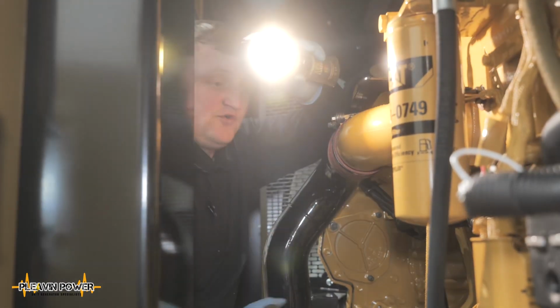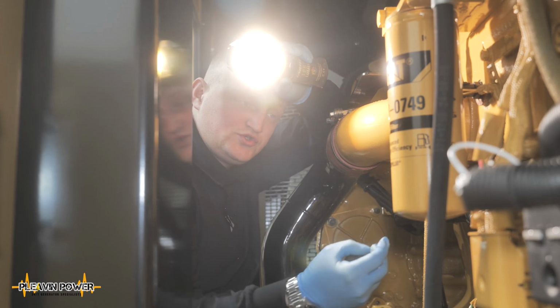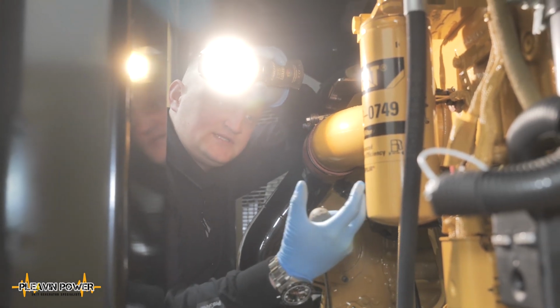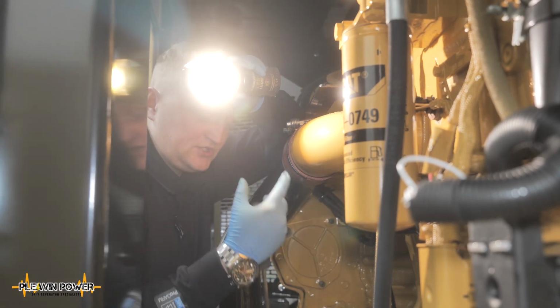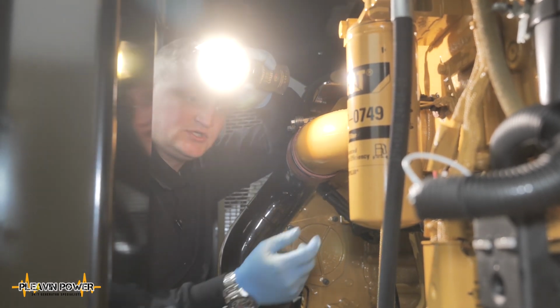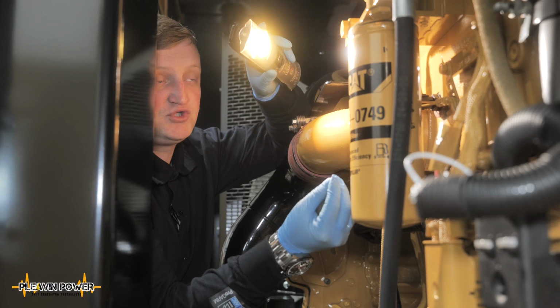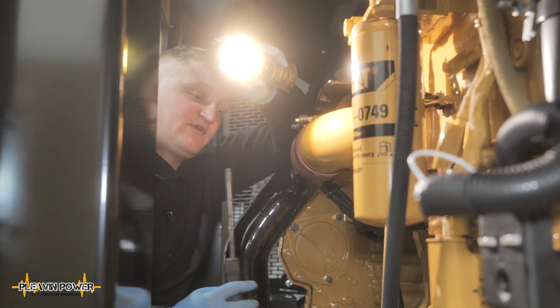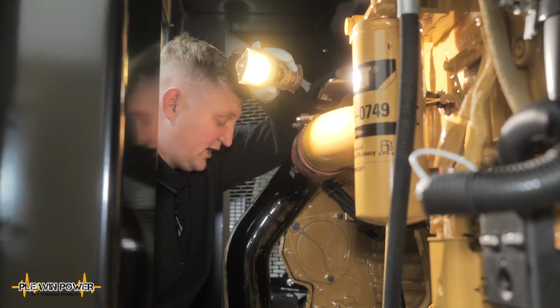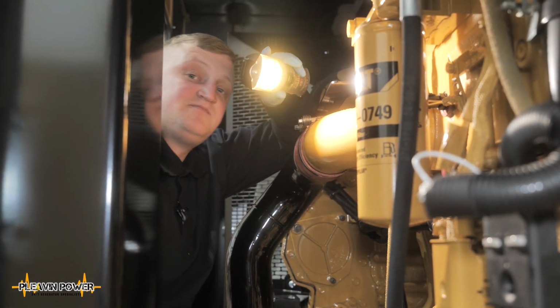Another thing that you've got to watch for is that if the filters are excessively old, such as 2 to 3 years, the filter elements inside can become damaged, and when the filter is put under extreme pressure, or even when the engine's just running under normal conditions, the internal filter components can collapse and block the supply of fuel to the engine in worst case scenarios. So it's very important to ensure that these are changed on a regular basis as part of any maintenance regime.